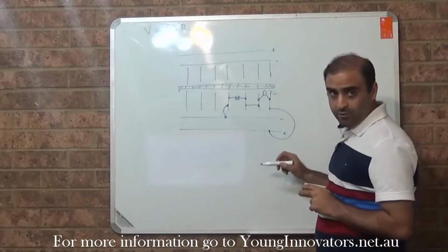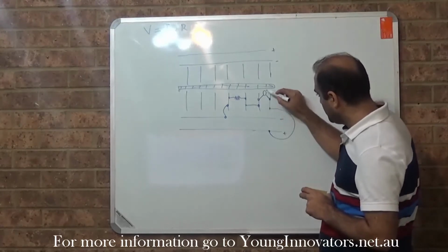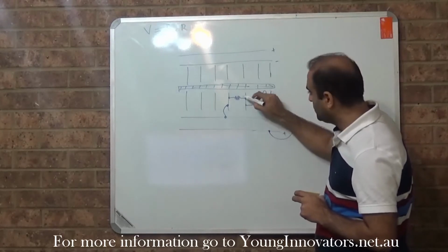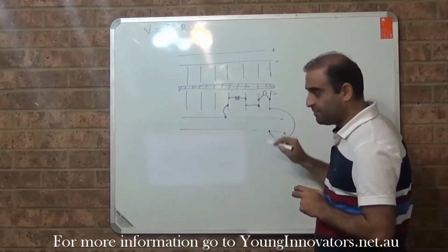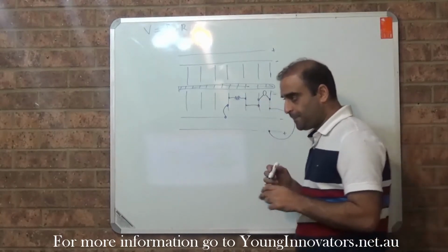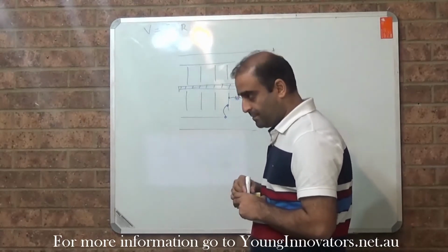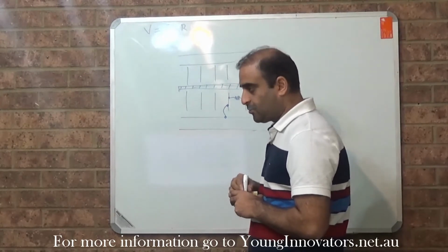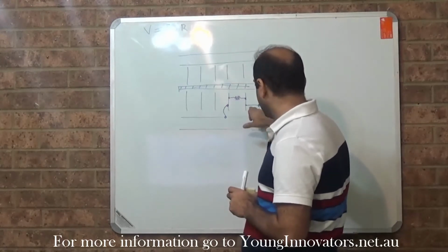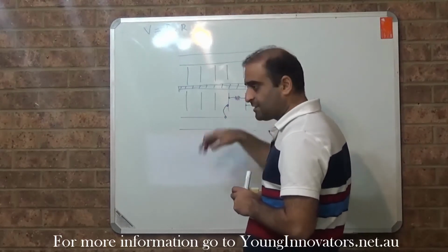So how will the current flow? Current will flow from here to here, go into the LED, come here, go to the resistor, come here and go to negative. So the current flows from positive to negative, right? Yep. So what it's basically doing, it's creating your own special wire, so you don't have to get your own metal wire and play around with it. Correct. So it just has the connectivity already done. Yeah. So you just connect the wires. You still have to connect these two points with wires, but the internal connections are already done, right?